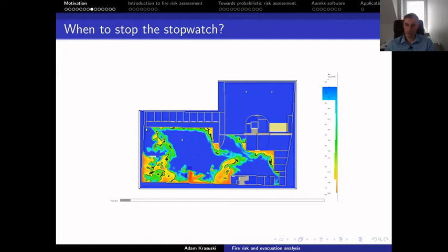For example, from this much more distant place we can still find a way free of these critical conditions where the people can reach the exit to the stairwell, and so on. Again, as experts, one group might say that evacuation is still possible and that this is not ASET, and the other group might say that evacuation is impossible and ASET was reached far before.